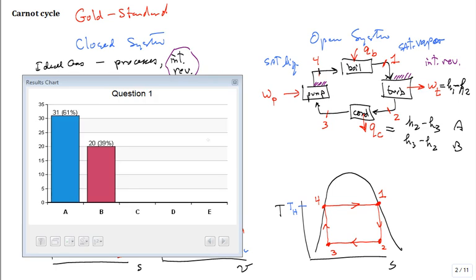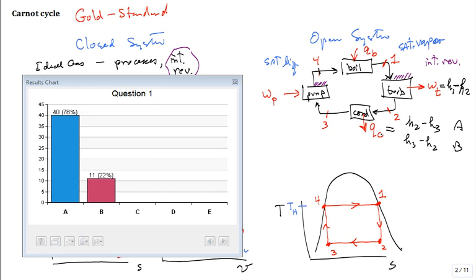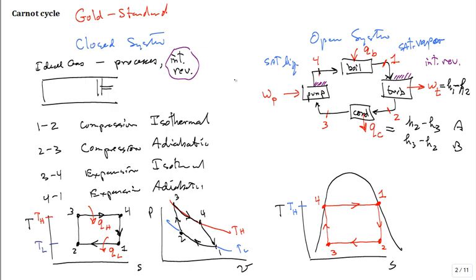All right. Oh, we have such a discrepancy. Why? Let me ask you this. Which enthalpy is higher, h2 or h3? h2. It's higher quality steam. I'm going to have to condense it. I'm going to take energy transfer out, right? And which direction is Q sub C shown on this illustration? Out. It's a positive entity I'm trying to talk about. It's how much heat is rejected. So which one will give us a positive Q_C? A. Oh. Thank you for participating.